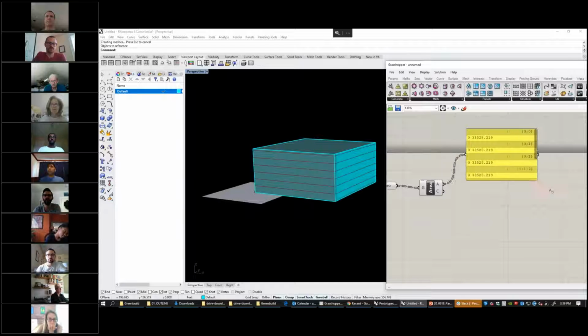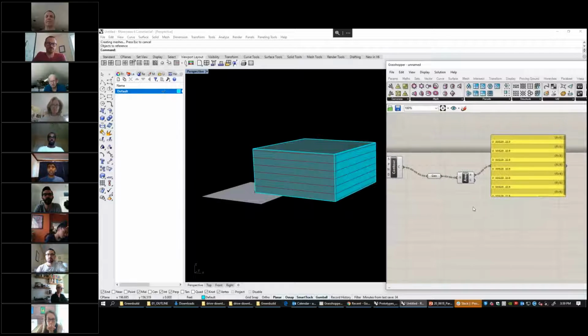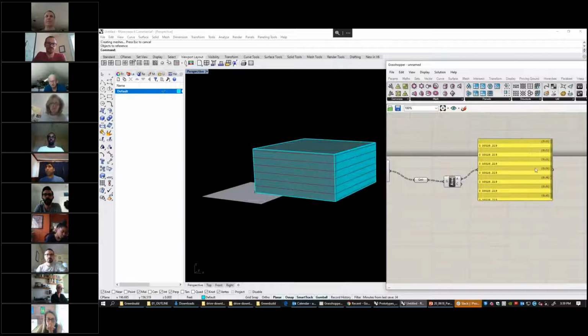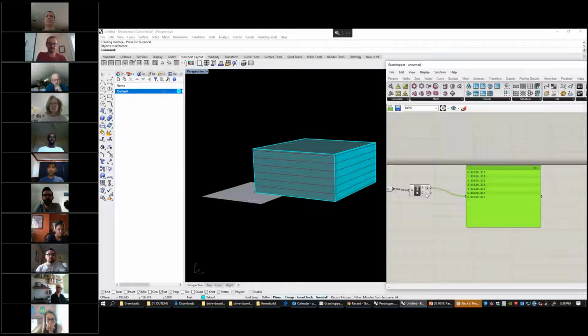And you see that it's broken up right now. There's a bar under here, a bar under here, a bar under here, so it's not one big list. If we right click on the A and do flatten, we flatten these multiple lists into one list. Let me do 2 versions of that just to explain the difference.